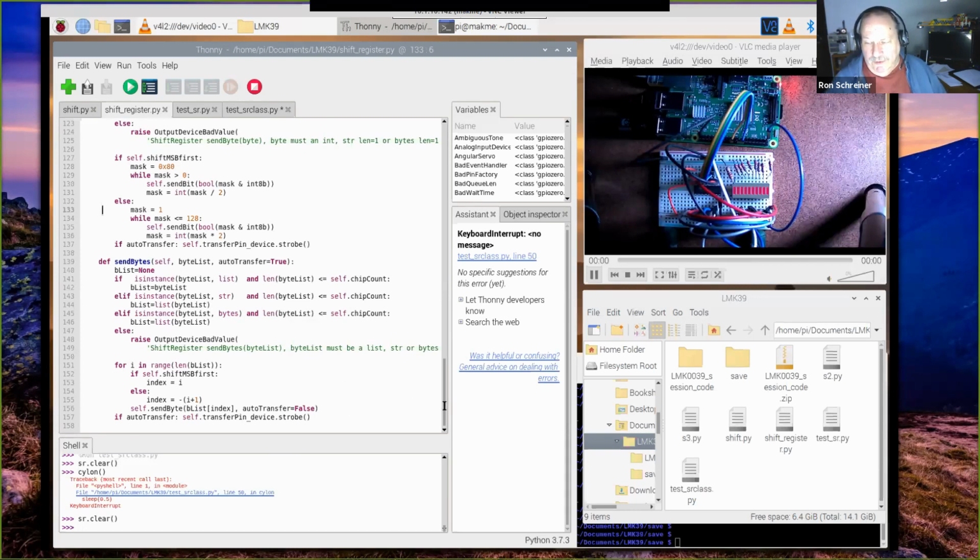And so the last thing that I need to add, which I haven't got to, is I want the ability, down in the gpiozero library, they have objects and modules that will manage threads, like in the LED stuff or the pulse width modulation stuff. You can synthesize pulse width modulation on pins that don't support it in the hardware. They start up a thread and let the thread handle the timing on that pin, and then it comes back to you, and your program can go off and work on other things.